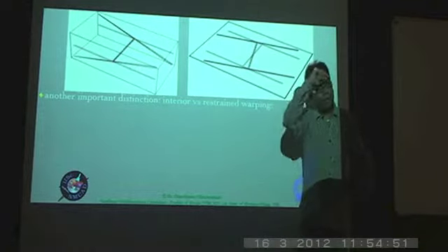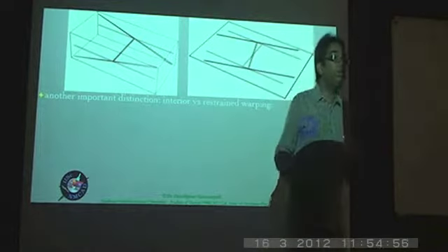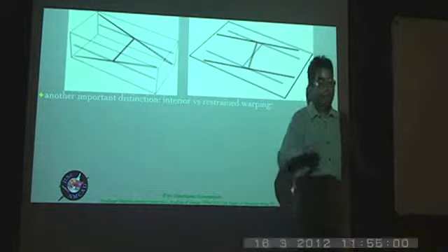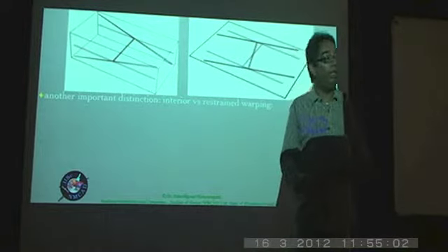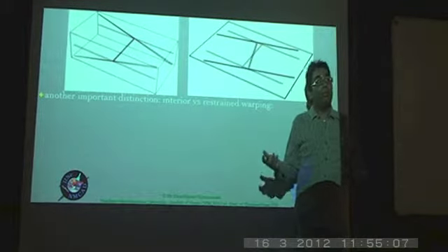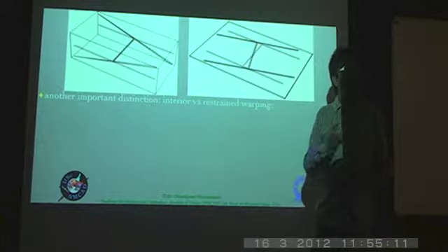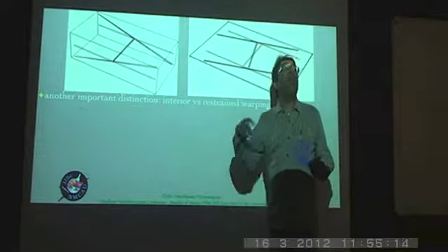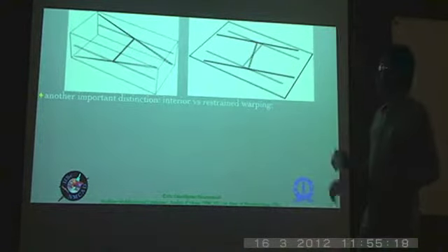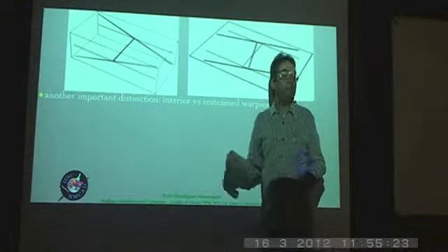When you have something like that, the resultant force is zero, the resultant moment is also zero, but you would still see the effect of that permeating through the I section. And that is a classical example because of the dependence of the energy, that is the one-dimensional energy of the beam, on kappa 1 prime. If you were to ignore the dependence of the energy on kappa 1 prime, you will not be able to extract that kind of an effect. Another important distinction is therefore between the so-called interior warping and restrained warping.